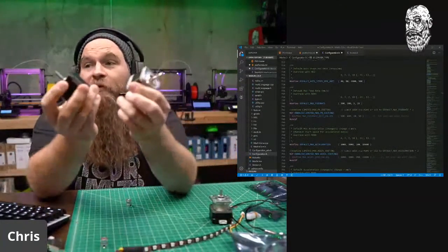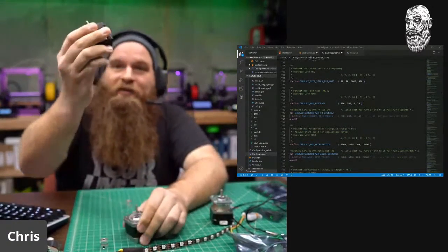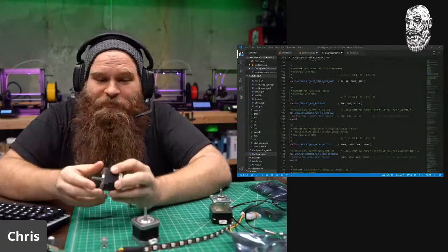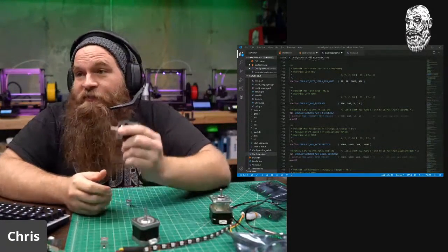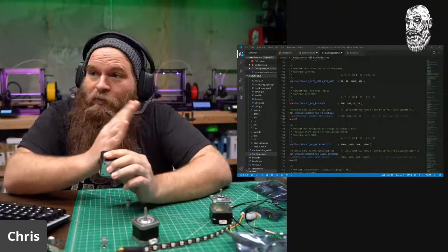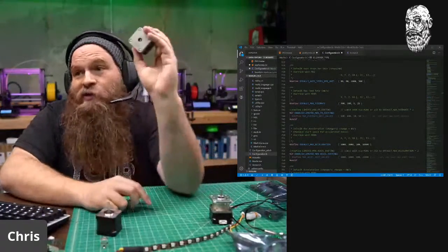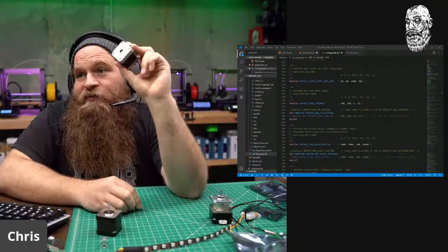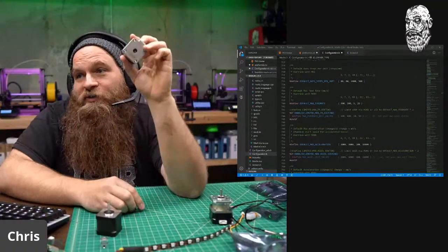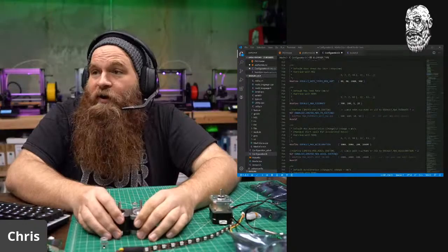So your most typical motor is a 1.8 degree hybrid stepper motor. It has 200 steps per 360 degree rotation. Pretty simple. How do I know this? It's just a fact. 360 divided by 1.8 degrees is 200. So it moves 1.8 degrees per step, and once you move all 200 steps, you move 360 degrees. A 0.9 is twice the resolution. It moves 0.9 degrees per step, making it 400 steps per 360 degree revolution. Well, that was fun, right?